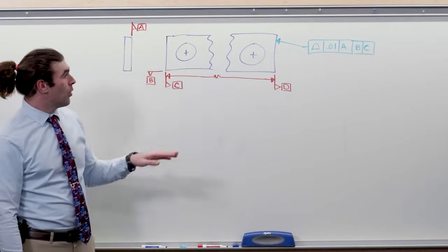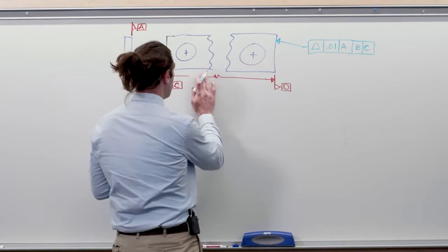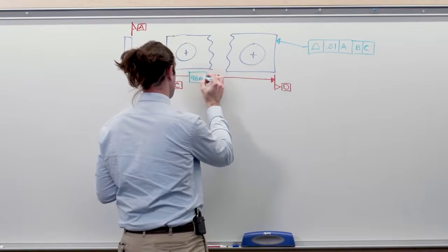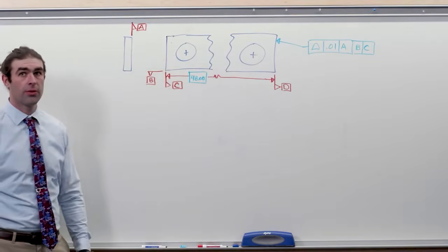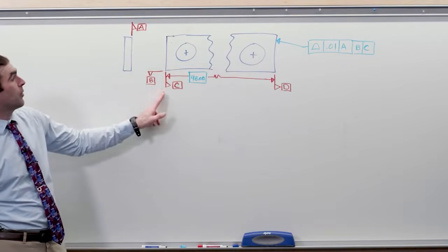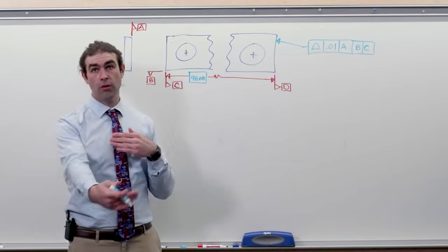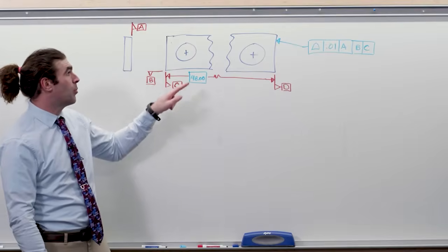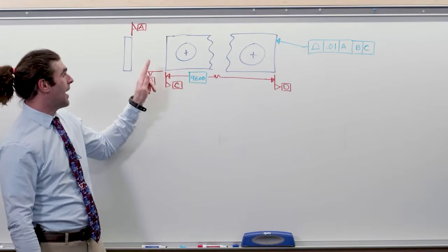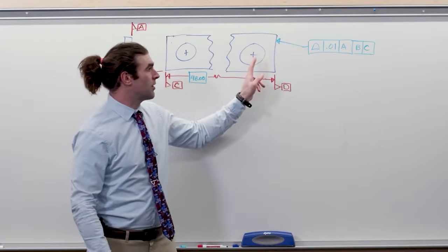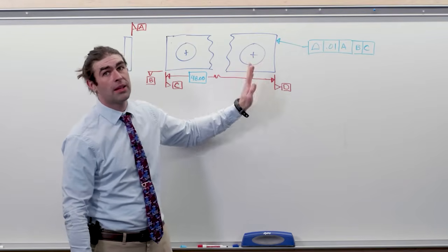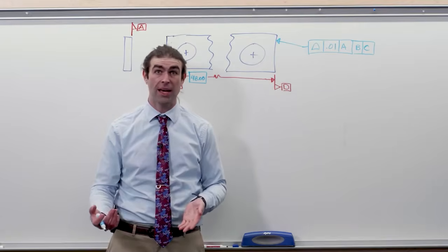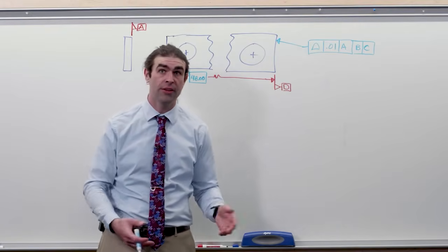Now, we're going to use a basic dimension here. Say it's 48 inches, okay? So we're going from datum C to datum D, the overall length of the part. The idea is we would want to have a position for this hole to A, B, and C, and the position for this hole to A, B, and D to make it slightly easier to inspect and functional enough.